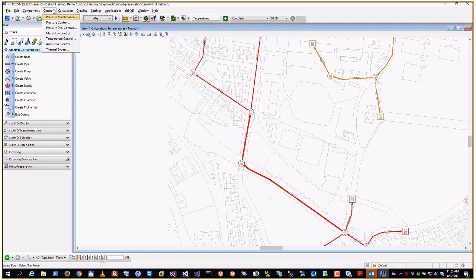And this information is entered via the controls dialog box. There you find at the top one more information, that is the pressure maintenance. When we carry out the computation, we need at least one node at a known pressure level, or in the network for pressure maintenance, maybe there is a medium pressure, a middle pressure between two nodes. That is the information to get one fixed pressure.